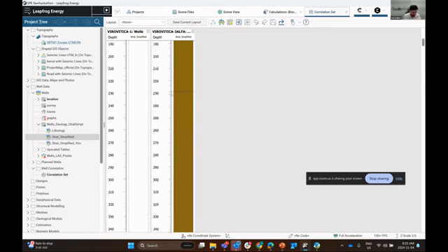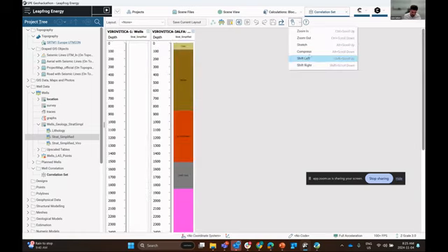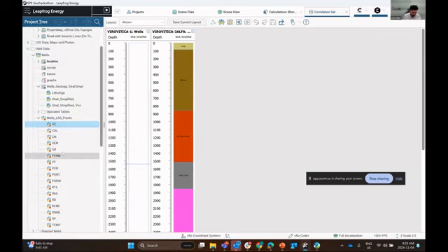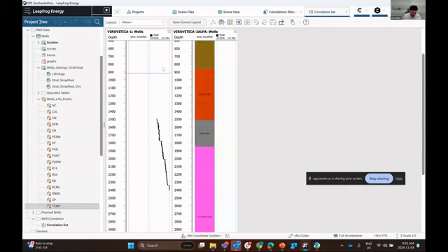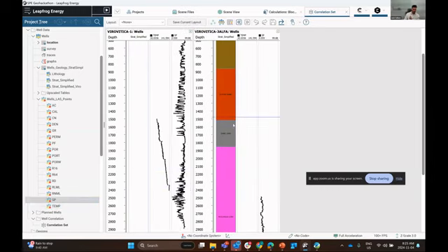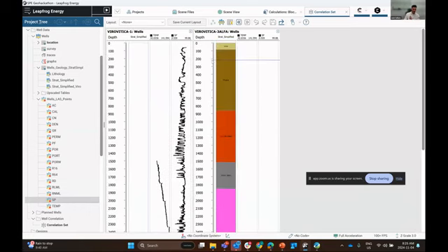You can press Alt and scroll to compress. So Alt, which is also shown right here, Alt and scroll down. And then you can start to add multiple different points associated with the drilling information. So you can simply just left click and drag from the project tree multiple physical property values to construct a well correlation set.